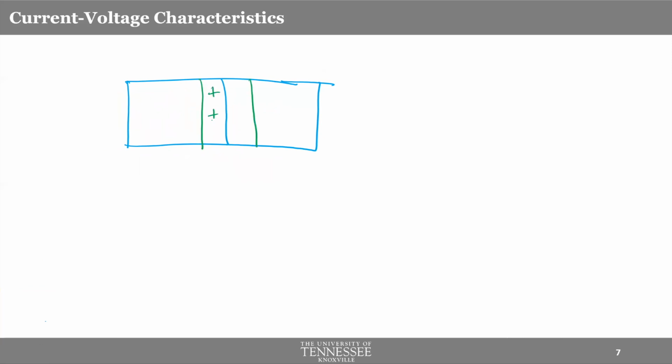So you have, say, positive charge and an equal amount of negative charge here, and because of that you have an electric field. Now once a hole goes all the way to the depletion region, the electric field works on the hole in this direction. So it throws the hole like this, in the same direction as the electric field.